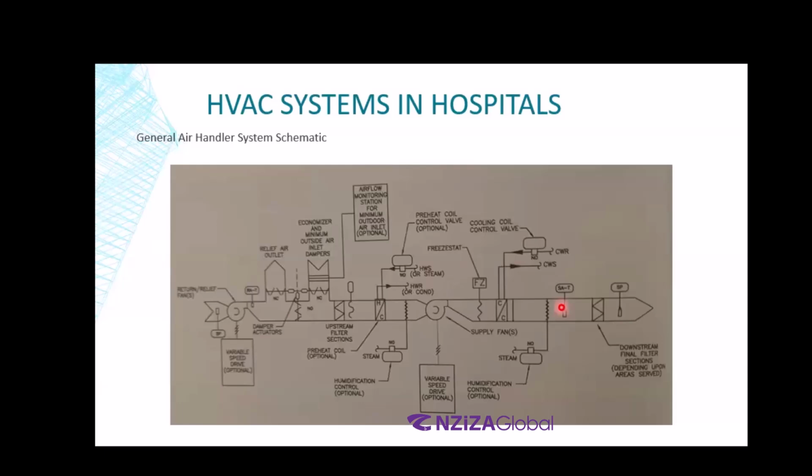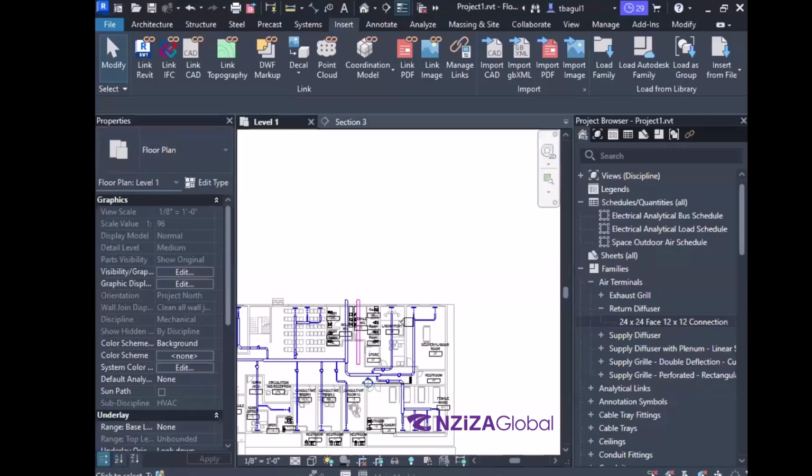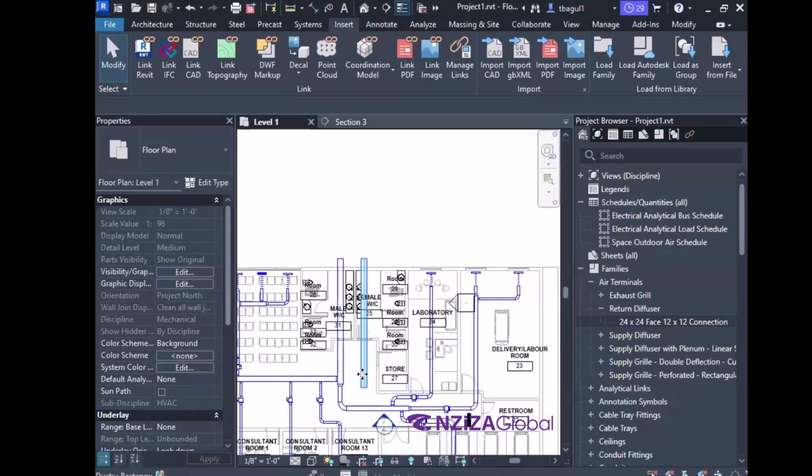Yeah, from the left, what is coming is the pink color duct, right? That air will go back to the air handler, right? Now, let's say in this case only 785 cfm that we were considering for the 3 rooms. We have a question, basically clarification, whether this end of the duct that we are seeing over here is the duct going back to the air handler, the return air duct.